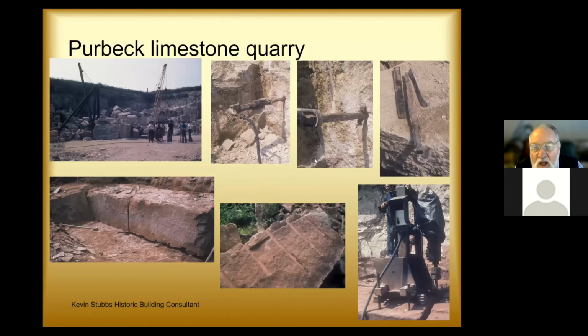Then you used feathers and a wedge: the feathers were slotted in the hole, and then the wedge was driven in along the line, and this split the stone from the bed. These days, this is all done pneumatically, but in the past it was done by hand. And the vertical cuts today are made by a drill that you work sideways into the face.